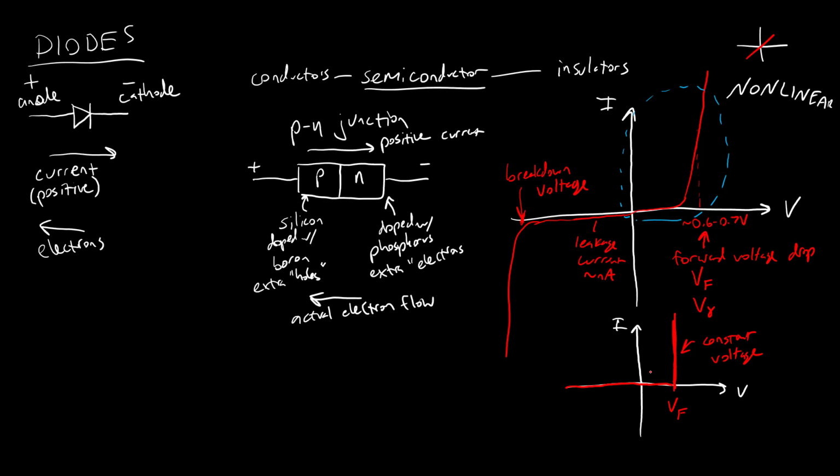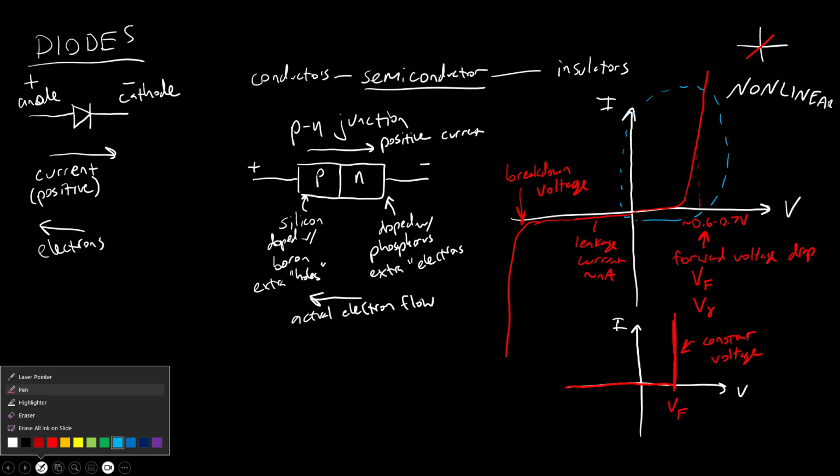But first, I'm going to try and cram this all in one slide here, and then we'll go over to a new slide. A mechanical analogy that is very helpful here, if you're a mechanical engineer, this series is really made for people who are not electrical engineers, is to think of a one-way check valve with water. So here's my little sketch of a flap that can open in a pipe. If I have water flowing through, and there's enough pressure on this side to push open that flap, then water is going to flow through that way.